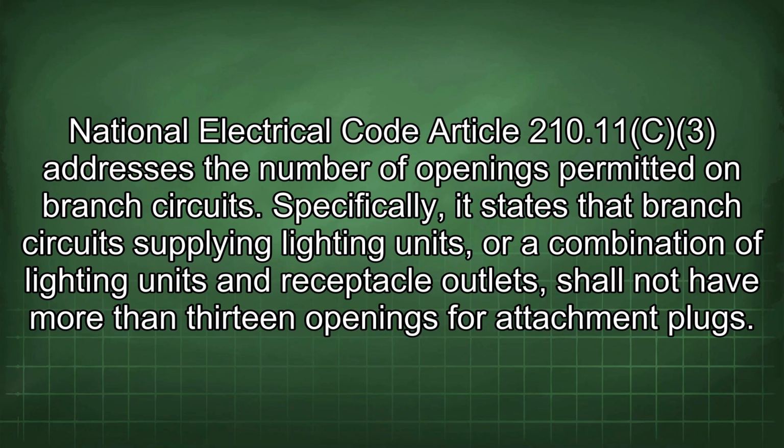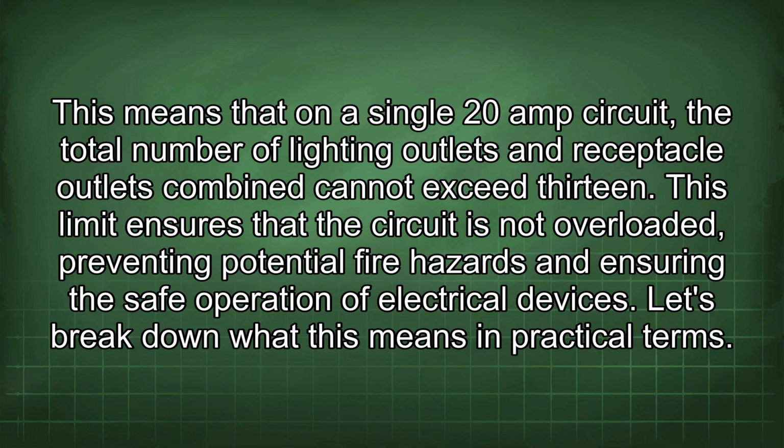National Electrical Code Article 210.11(C)(3) addresses the number of openings permitted on branch circuits. Specifically, it states that branch circuits supplying lighting units, or a combination of lighting units and receptacle outlets, shall not have more than 13 openings for attachment plugs. This means that on a single 20 amp circuit, the total number of lighting outlets and receptacle outlets combined cannot